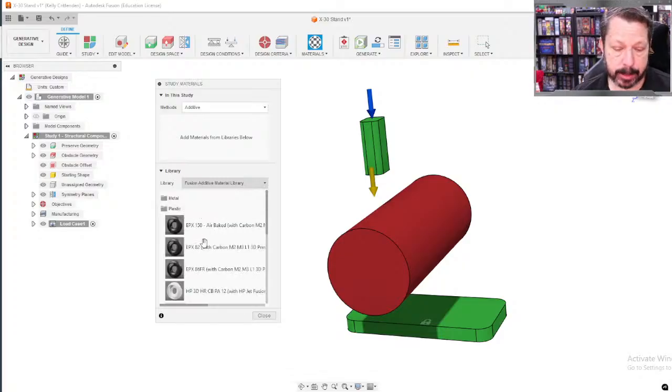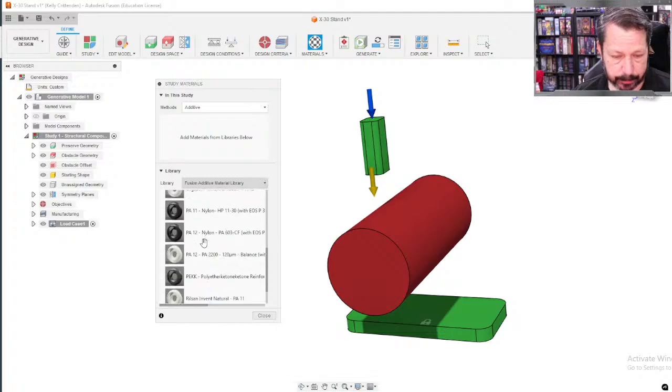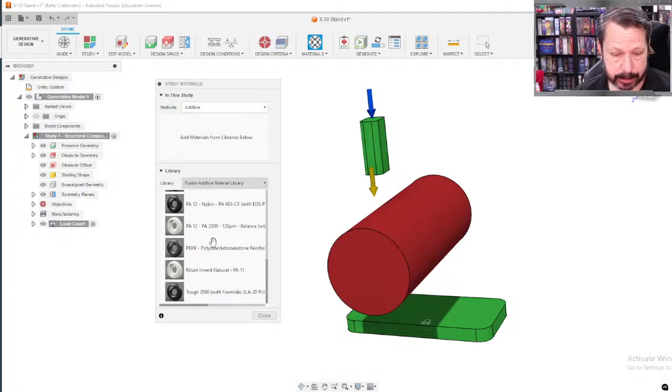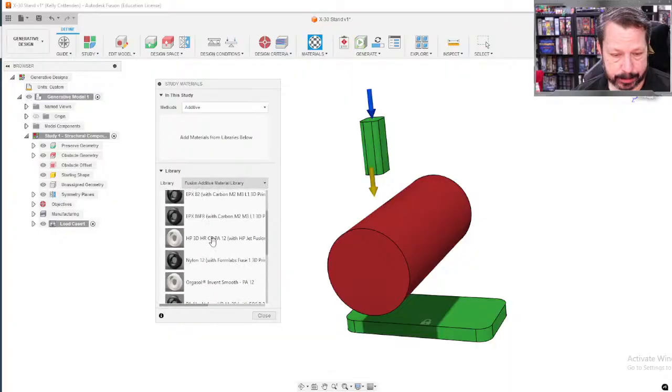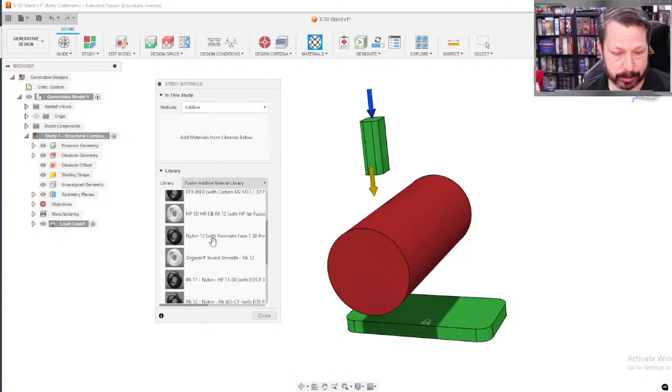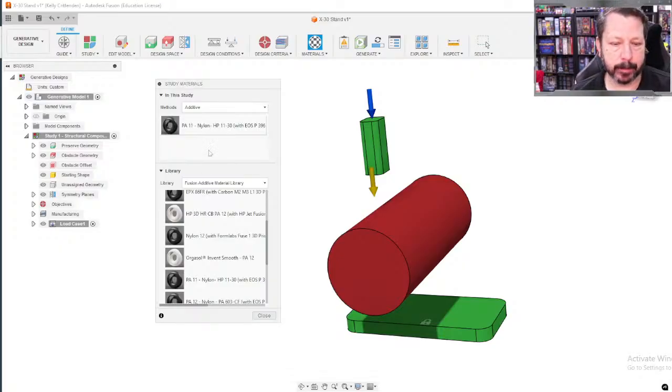Now again, these plastics are not FDM plastics. These are all, well actually, these are really tough materials. What's the closest I see that we could actually print on a printer here is this nylon, maybe the nylon 11. Now these are not the nylon that we would print, but we can print a PA11. Actually, I think a lot of times it's a PA12. I saw one here, there's a nylon 12. But these are resins. So that's close-ish to some of this stuff that we can print on an FDM printer. These others don't look close at all.